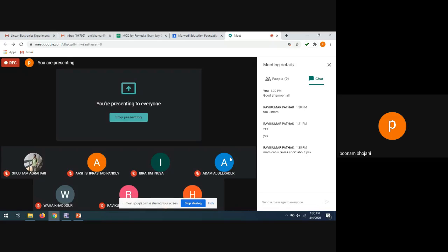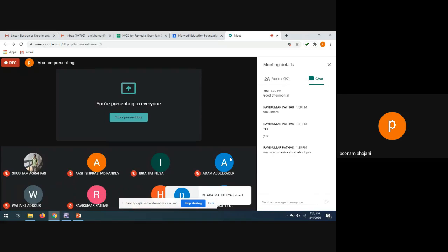For that we have also seen the constellation diagram, if you remember. In that diagram we saw how the four different phases are assigned to the different levels: for 00, 01, 10 and 11, four codes, we assigned four different phases. Here the phase is the one which carries the digital data, not amplitude, not frequency. In ASK and FSK, either amplitude or frequency carried the data, but here the phase tells you what the binary data is, either 1 or 0.